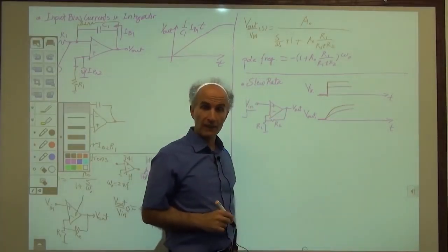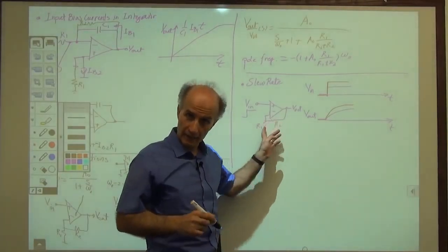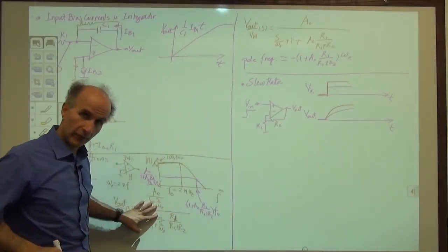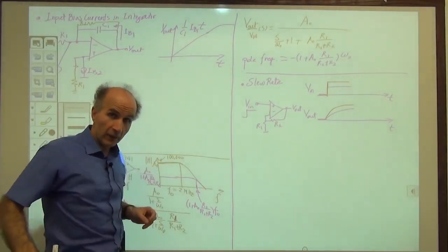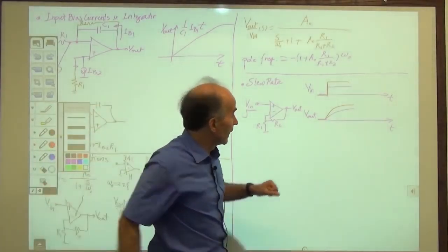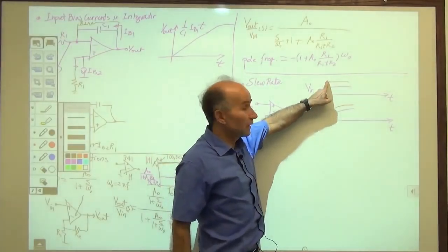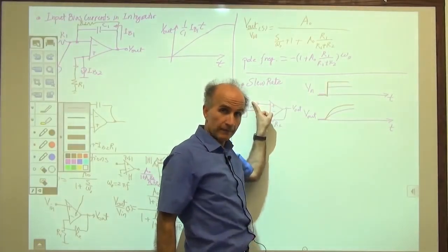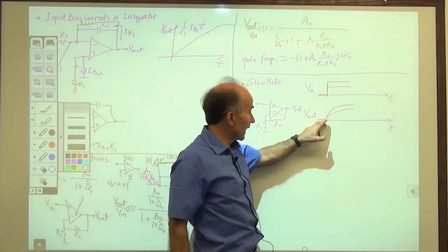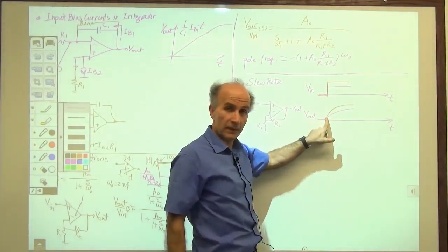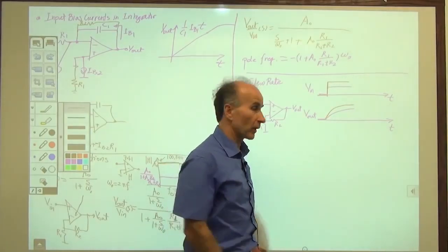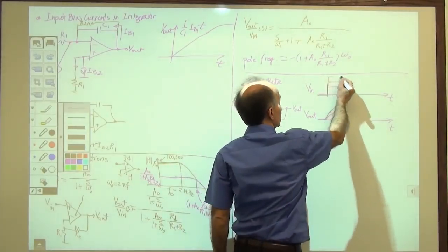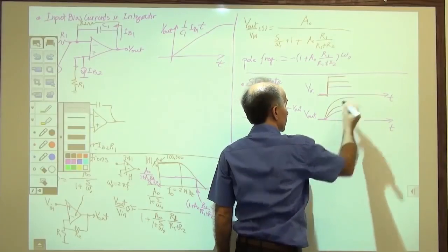So what's interesting is, if the op-amp has bandwidth limitation, according to first order system, but doesn't have any other imperfection, then as the step height increases at the input, this output has a slope that also increases. You see the slope and now the slope. All right, so if I increase this farther, then this also goes like this.